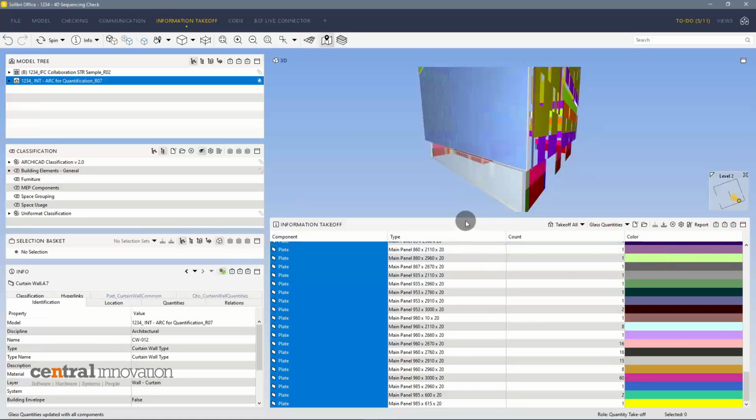And since in Archicad types are driven by translators, you don't have to have just one single list of types. You can have types for quantities purposes, and then types just for the sake of project development or construction or design coordination. So they don't need to be the same. Based on this, you have the ability to quantify individual levels, so good level of granularity.